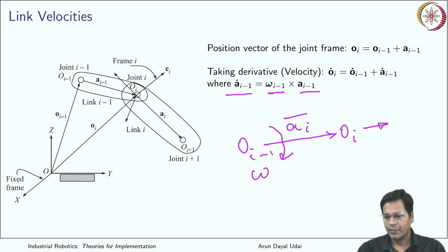Okay. So you can take the cross product of these two vectors and you can find an orthogonal vector which is like this. Got it? So this becomes your tangential velocity. This is your normal or axial velocity. This is your tangential velocity. So this is the direction of this vector, and this is due to the rotation of this link. And even if this is absent, this is always there. Okay, because your joints are moving. So if it is rotating, you see this vector.